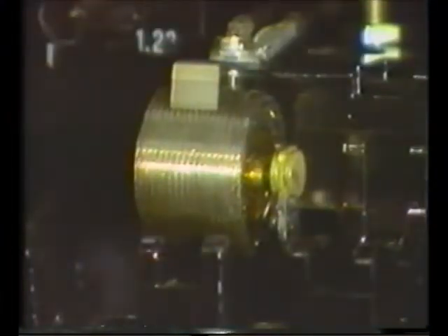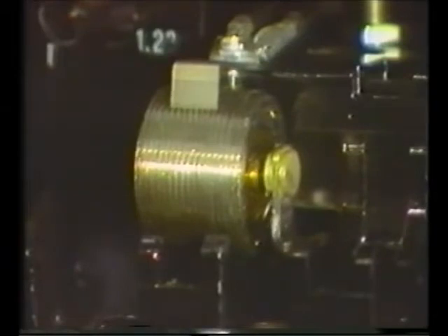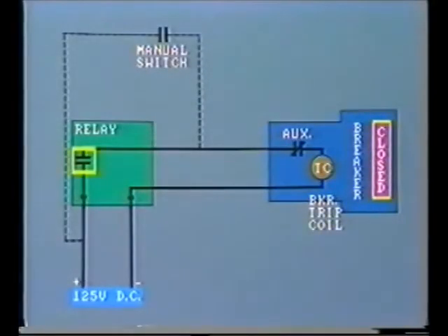But it is possible that the relay contacts may bounce open first as the fault is removed by opening the breaker. These delicate contacts inside the relay are not made to interrupt this relatively high current flow through the tripping circuit. So in order to protect the contact surfaces, a seal-in arrangement is usually wired into the relay. It functions like this.